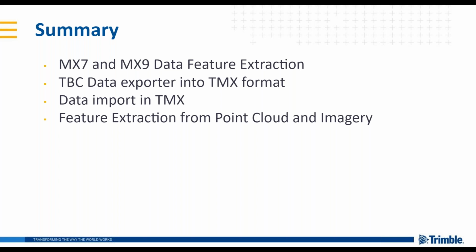Can we use the drafting methods for area point clouds? Yes, for sure. These methods are available for any point cloud; they work on any point cloud, not just mobile mapping. Another question: how can we extract traffic signals also? You can extract them manually just by placing a point there, or with the automated tools, which we'll be discussing at another webinar. There will be another webinar for completely automatic tools, where we'll discuss more on the traffic signals and also the pole extraction.